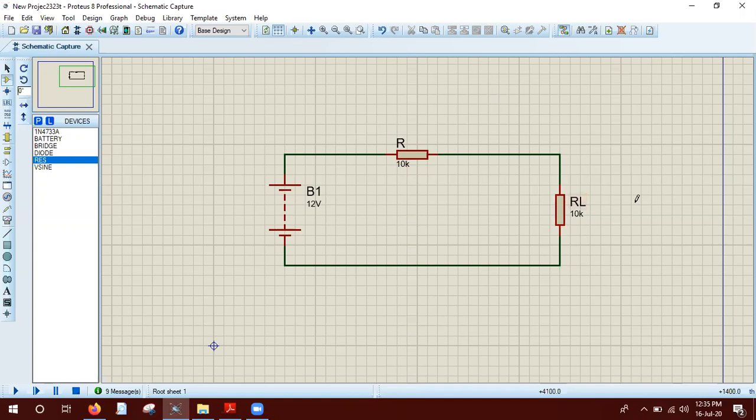It should be the rest of the voltage, because that 10k ohm resistor, the normal resistor, will drop a voltage. So that drop voltage, you subtract from the source battery, and you get the rest of the value for VL. Yes, I know that, you are telling about the process.